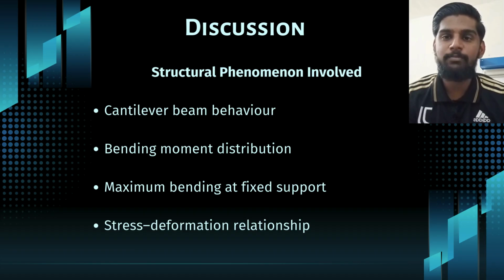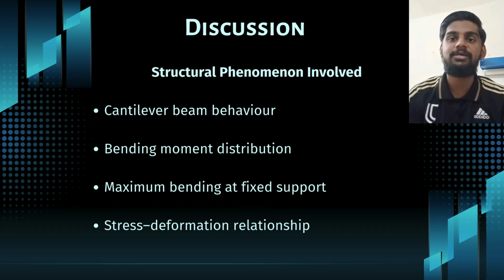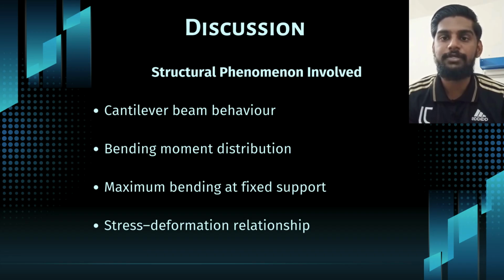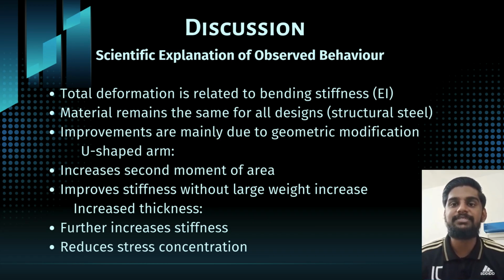The applied bending moment also causes bending deformation, with the maximum deflection occurring at the free end, which is the VESA mounting plate. Therefore, the stress and deformation patterns observed in the results are consistent with fundamental beam theory and cantilever behavior.